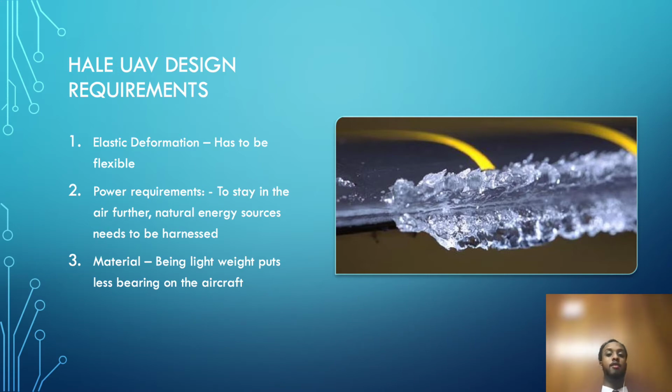So to start off with, the thin air at high altitude is cold due to the low pressure. Now at a height of 25 kilometers, for example, the ambient air pressure and density are around 2.45 and 3.26% of their average values at sea level respectively, while the temperatures are approximately minus 50 degrees. Now, these properties affect the vehicle's ability to generate sufficient lift forces to retain its weight.